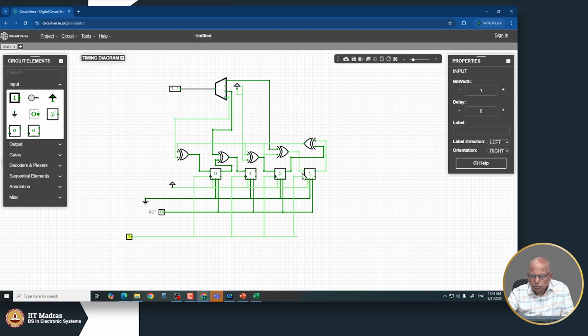So it went to 0101 state. The good circuit had gone to 1100 state. The stuck at 1 fault here sends it to 0101 state. So even 4 clock pulses will be sufficient to detect that there is something wrong with the circuit.